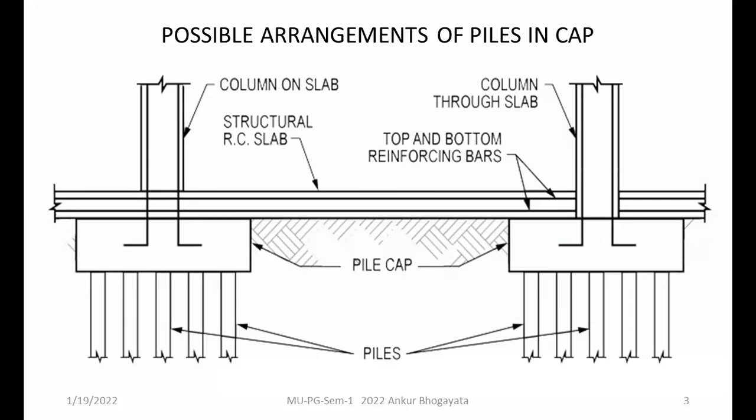The combination over here is shown with a simple illustration. When the adequate strata is not available, you are bound to use piles, but they are connected at top. And here the footing, let us say, an individual footing, is supported on a set of piles or group of piles. So they transfer the forces to the ground by means of the cap itself.